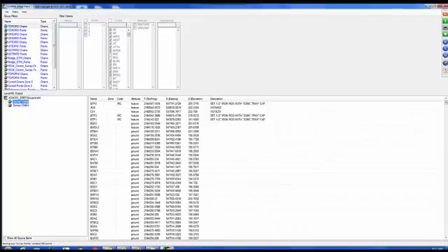When that becomes unlocked, now you have the ability to go in and modify the filter criteria for that filter. So I could check or uncheck any codes, or I could check or uncheck any, in this case, any attributes. Once you've made your changes, you double-click on it to relock it. Now, you remember how we looked at the survey points, and you'll notice that there are no zone.